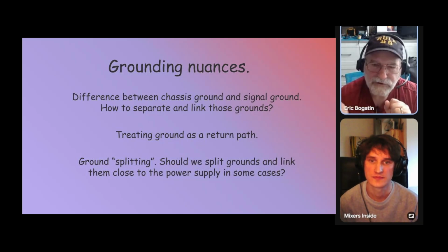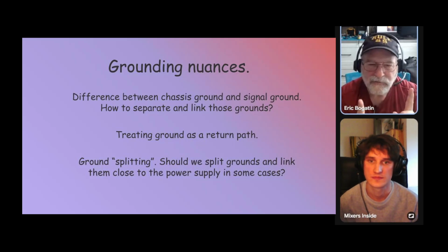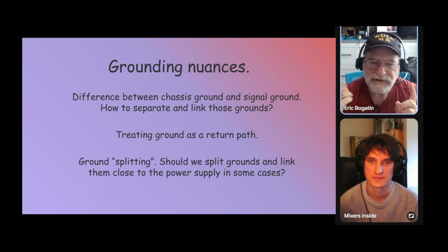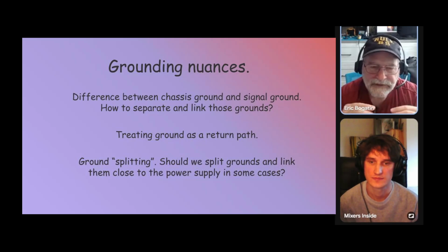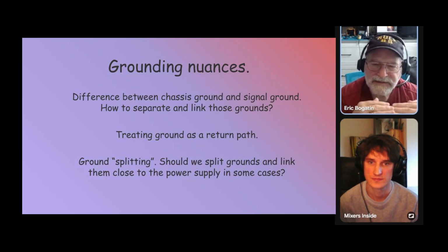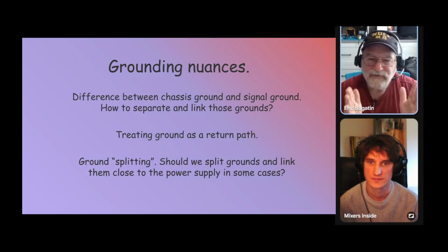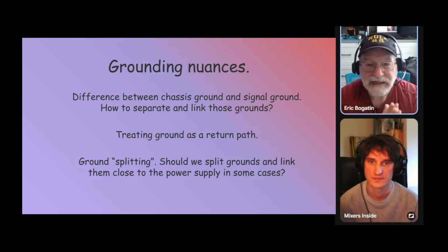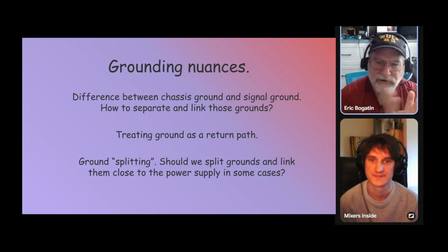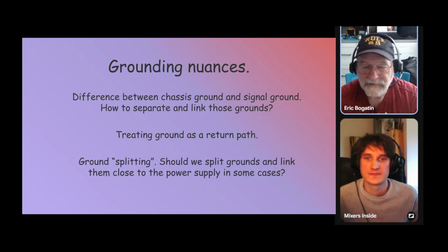If that return current generates a resistive voltage drop, and you modulate that current because the power rail has noise on it, the signal line that uses that same interconnect for ground reference sees that voltage noise on top of the signal. And that's exactly what you saw. Yeah. You got current from the power line. And I show an example of that.